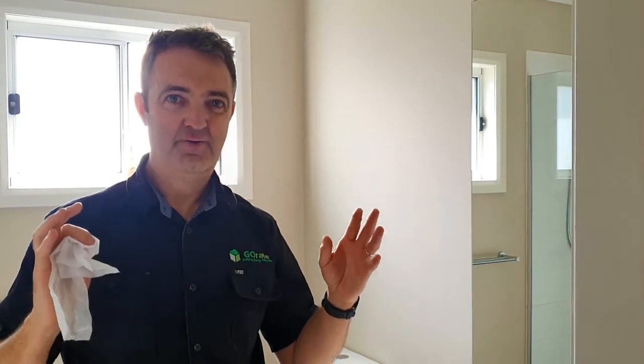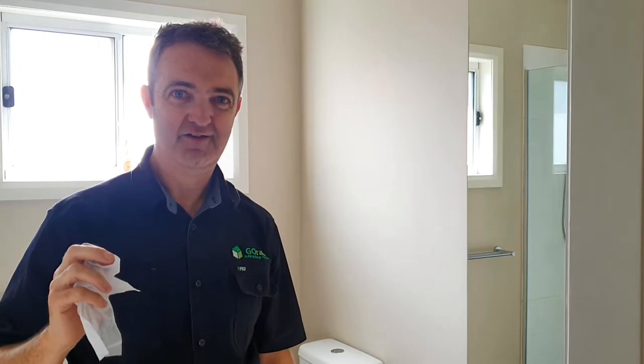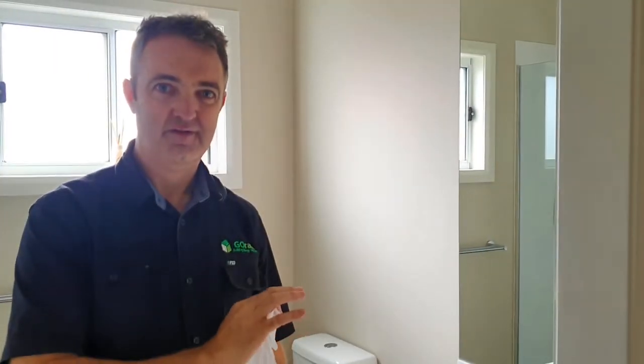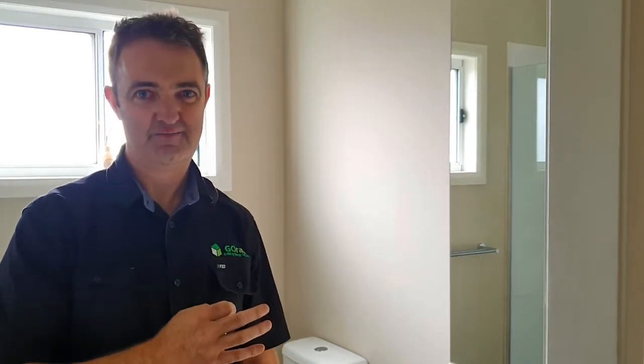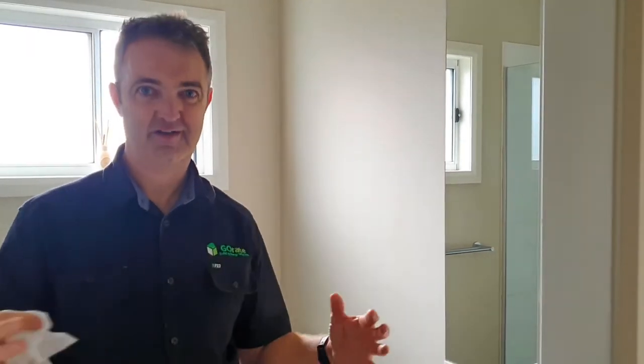What we really want to do with a high performance house is to contain the air. Once we contain the air, we can control the air. So if you're paying to heat or cool the air in the house, you want it to stay in the house. You don't want all that money that you've paid for going out through gaps and cracks and big holes. So the more we can do to cover those holes, to seal them up, the more chance we have of keeping that air inside. So all the money you've paid to heat or cool stays inside the house.